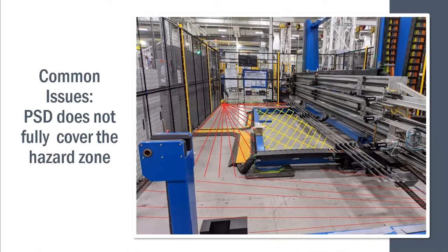Obviously when it's not running, you can go in, and a light turns on the laser scanner when it is being triggered. So you can move around and verify that the laser scanner is seeing you. In this case, I got inside of this space here and it was not seeing me. So somebody could stand in here, and the laser scanners aren't going to know you're in the space. Somebody outside could start up the operation, and this apparatus can slide over into you.